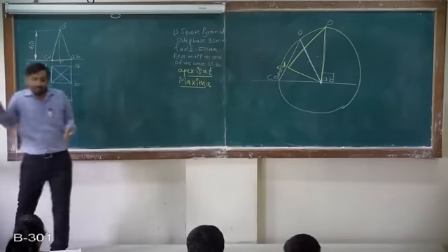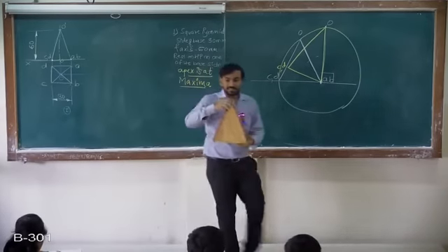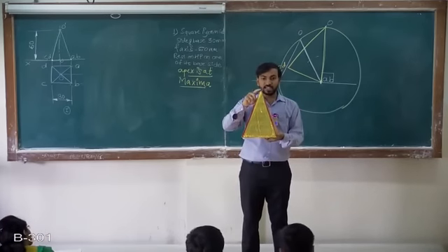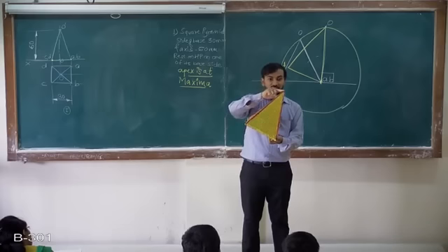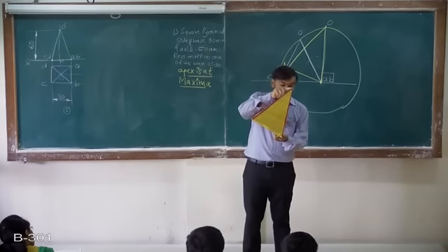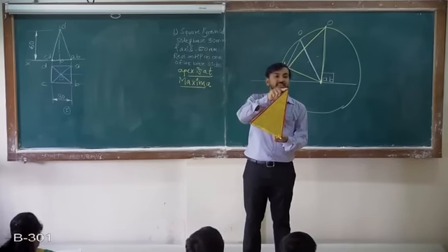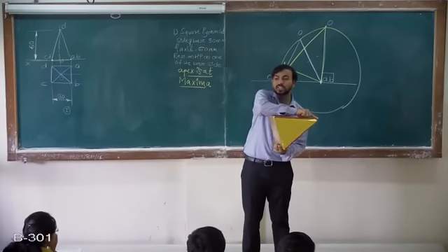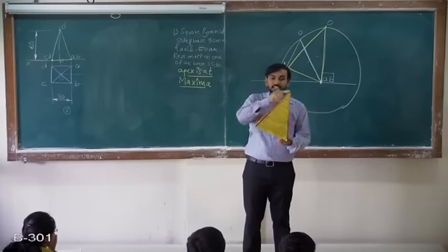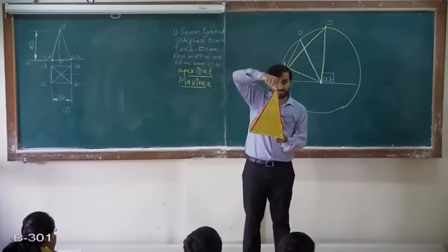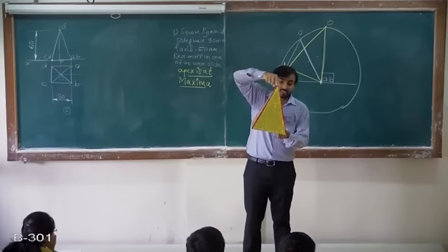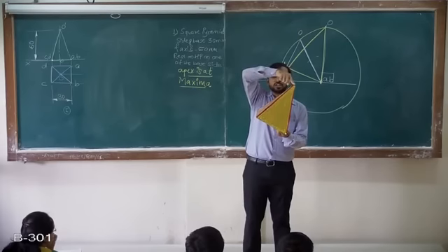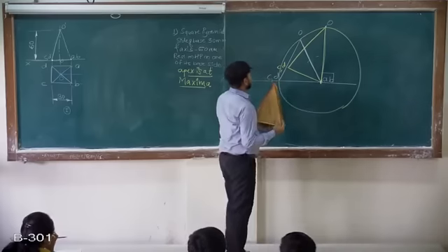Now you can see, that's why I had this slightly enlarged dimension of the prism. First you see the apex and now observe the position, keeping this fixed. This is a slight arc. When this is exactly perpendicular, apex is at the highest position. And then it will again go towards HP. So I need the highest position of this O point. That means simply this face should be perpendicular to HP. The logic I explained like this.